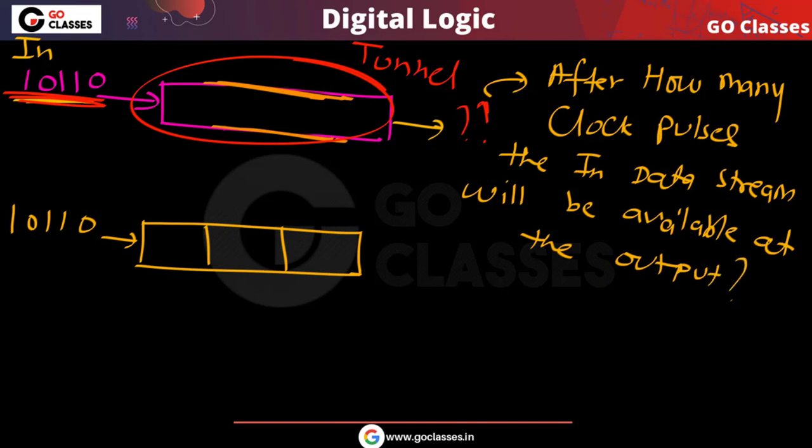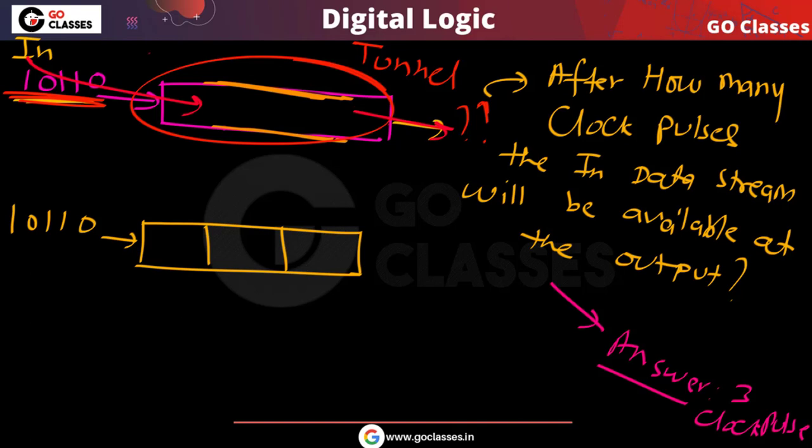So this is the question. This input data stream, when will it be available here? The answer is 3 clock pulses. After 3 clock pulses, this data will be available here. Basically, you are going into this tunnel, and after how much time you are getting out of this tunnel, this is the question.